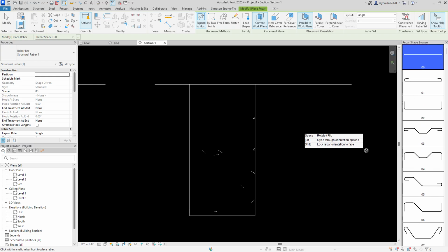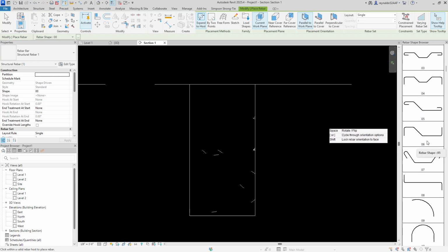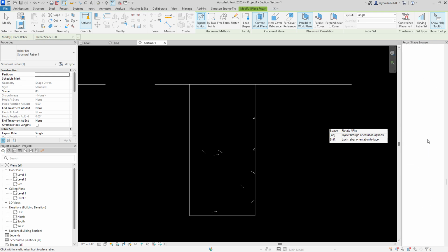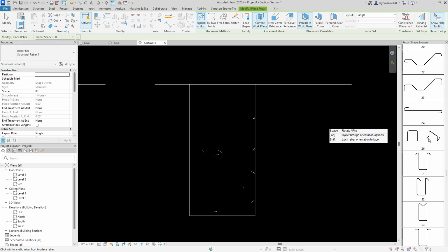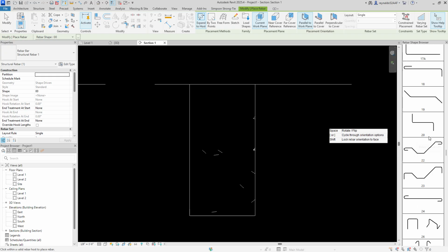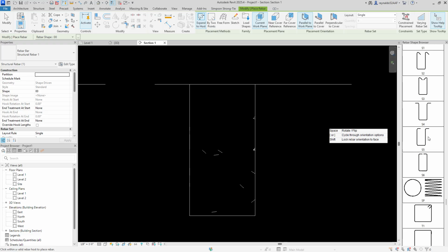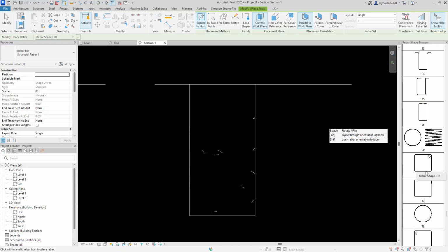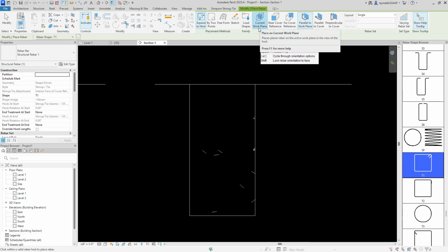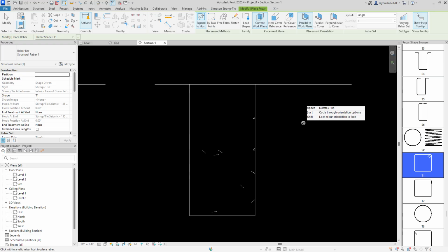So to start setting up the rebar, I'm gonna do some stirrups, which are these, so you guys can see them in 3D. I want to do, let me see, which one do I want to do? I think I might have passed it. I'm going too fast here. I want to do this one here, number T1. I'm going to click on that one, and you want to make sure that you want to be on the current work plane. The current work plane would be where you made your cut through your beam.